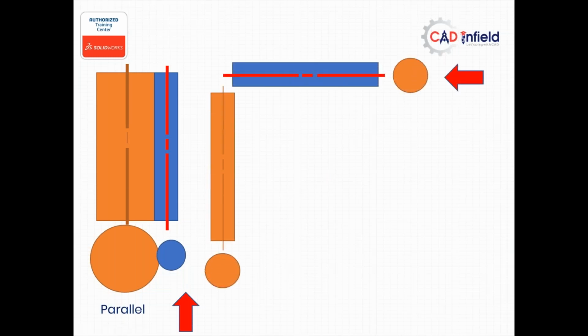Next one. Here we have two shafts. The second view I have drawn, either you see from the bottom or from the right. I have mentioned the direction also. Here, if I extend this shaft axis, after some time it is going to intersect with the other, and the angle between these two shafts is 90 degrees, or any angle. Bevel gears you can get in various angles, but assume the two axes of the shafts are intersecting and not parallel, because parallel means the angle is zero.